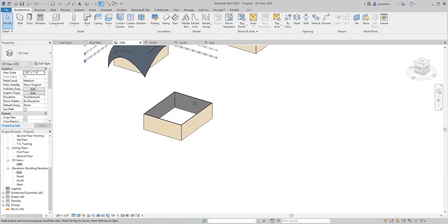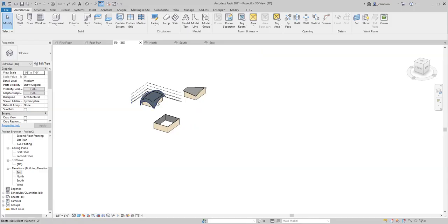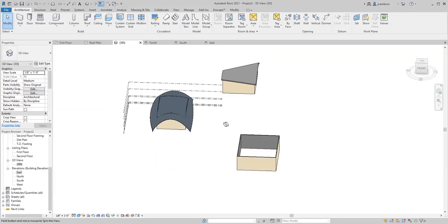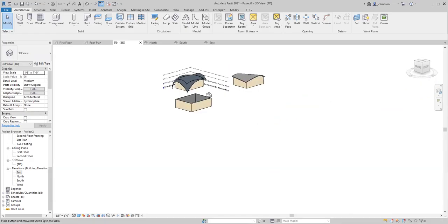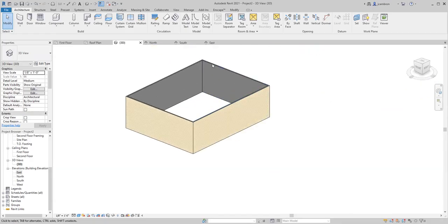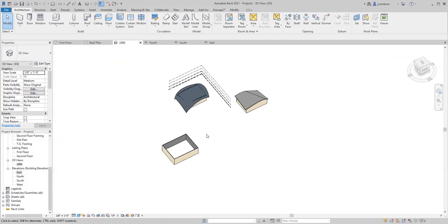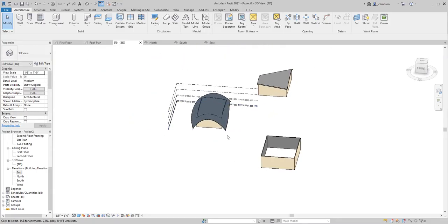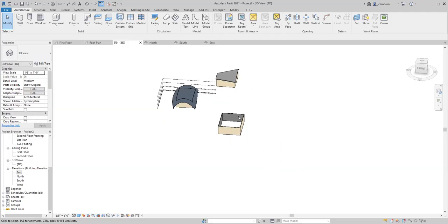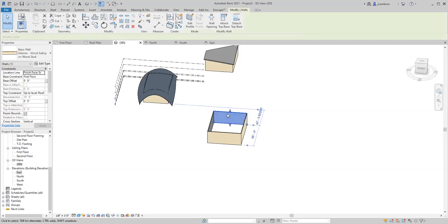And let's orbit. Okay. By the way, a little trick when orbiting. If I'm trying to orbit around to say the other side of this wall, it becomes really difficult, right? Because I'm doing an orbit around everything. A little trick with the orbit tool is if there's something you want to actually orbit around, you simply select it.